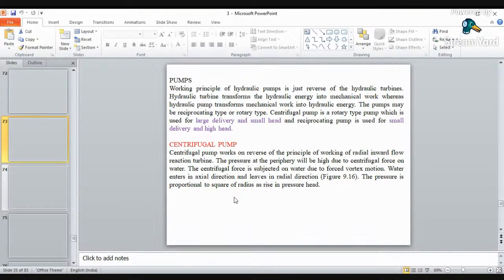The centrifugal pump is used in agriculture, municipal corporations, industry, power plant generation, and petroleum. When a certain mass of liquid is rotated by an external source, it is thrown away from the centrifugal axis. And the very name centrifugal means away from the center, that is the centrifugal force. Here also it works on the same principle. The water or liquid will be thrown away from the axis of rotation and head is impressed, which will enable it to rise to a higher level.